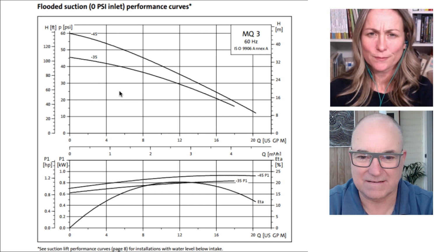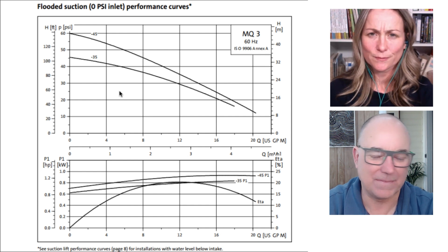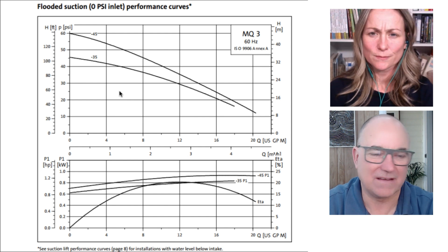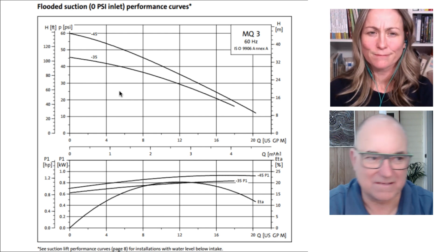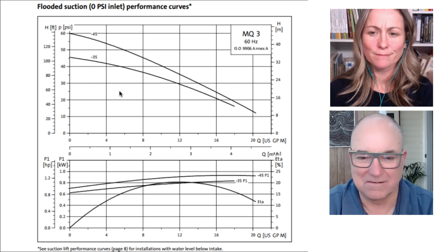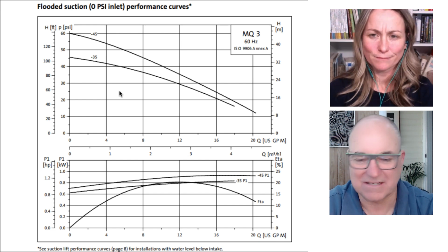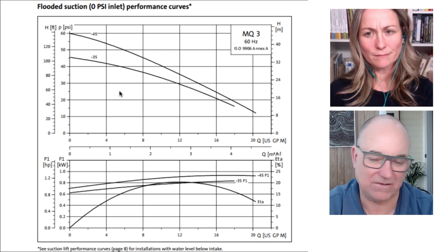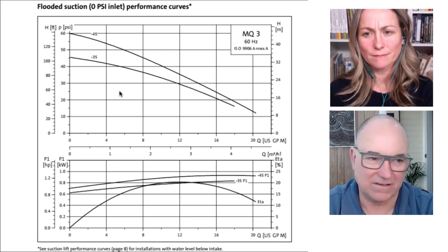We only choose a different pump or different configuration for a pump if the site is unusual, if there's a big hill, or it's a 4-story house, or something quite different. You normally end up with something that works for you and a feel for how the numbers work.